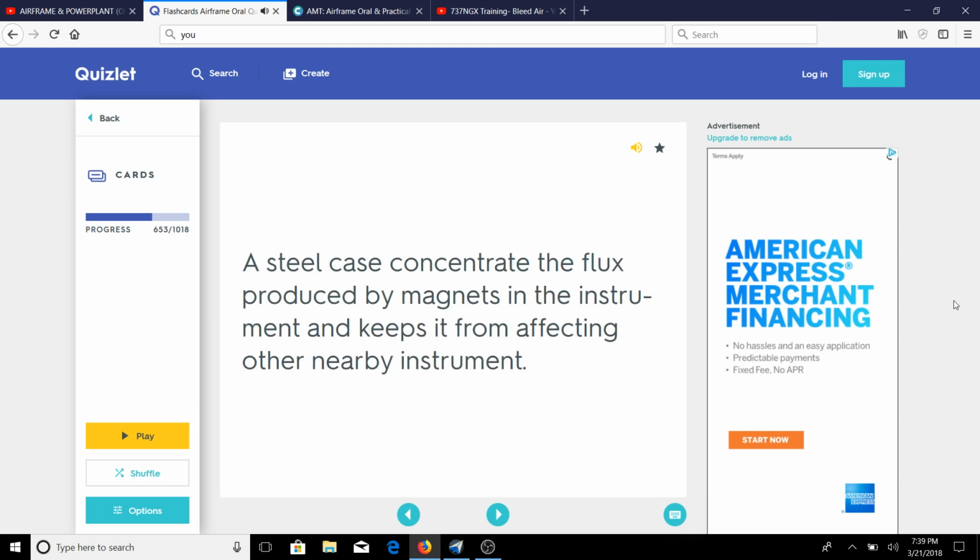What is the difference between a 2 minute and a 4 minute turn and slip indicator? A 2-minute turn indicator gives a 1 needle width deflection for a standard rate of turn. A 4 minute turn indicator has doghouse-shaped marks located 2 needle widths away from the center mark.